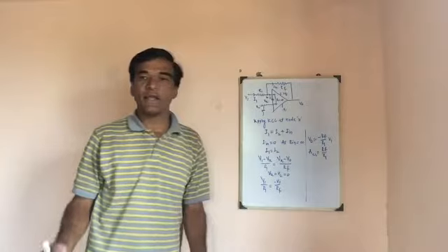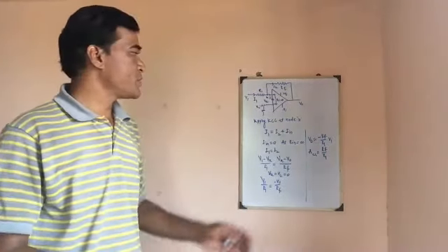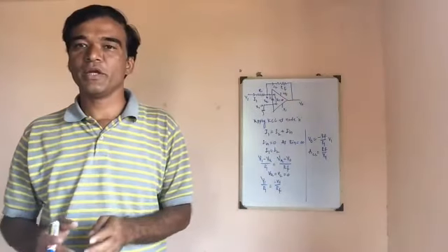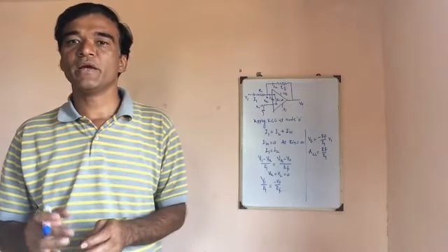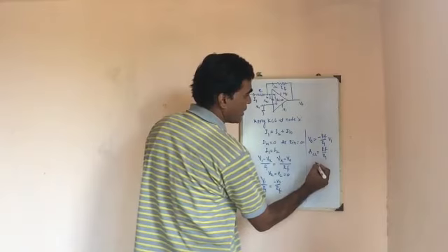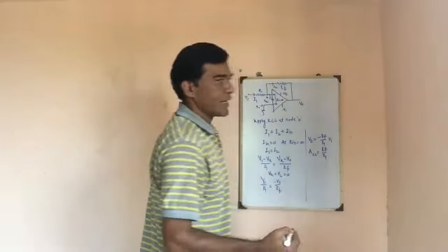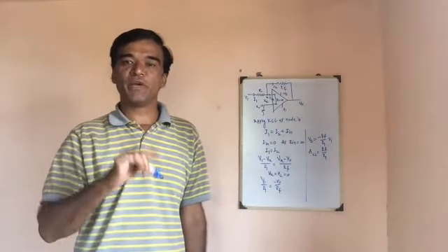So here the gain of the inverting amplifier is Rf by R1. Simply by choosing the values of Rf and R1, I can control the gain of the inverting amplifier in a closed loop. Hence this is the benefit of feedback. So here the gain I can write as Rf by R1, and the negative sign indicates that the output voltage is an inverted version of the input.